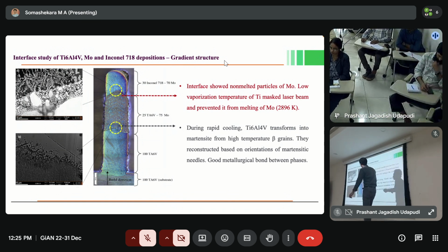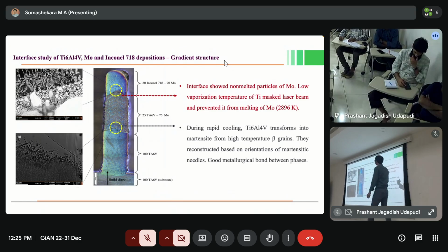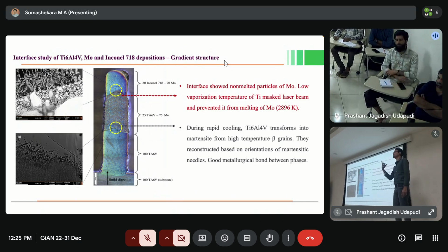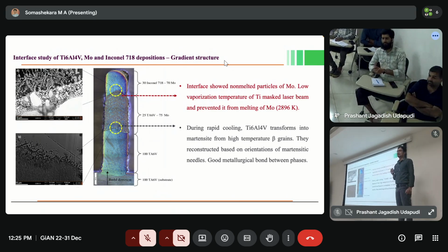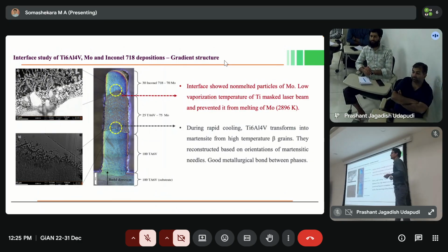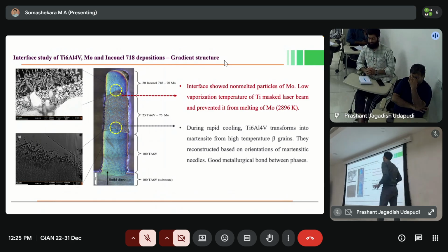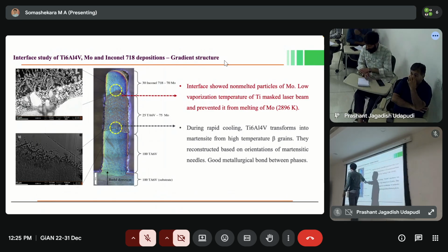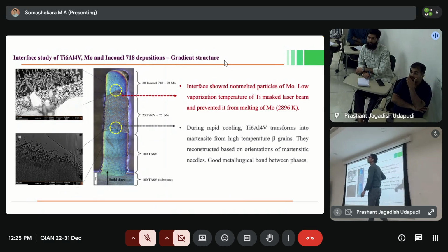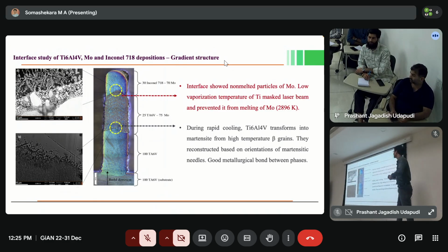So there you need to change uniformly. Start with just 5%, start with 2%, where you will not notice much. But if you do a sudden step, you will see a huge difference. Mainly you will see that the cooling rate of the material will be different, the solidification rate will be different. Some materials will have different cooling rates, so there you will find too much error.